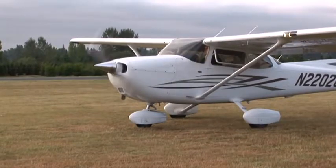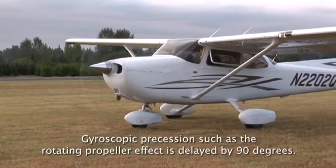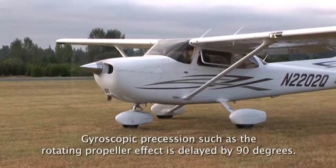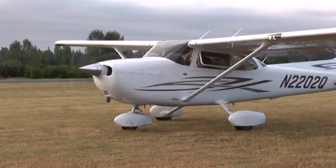Now, there is one other left-turning tendency that is often discussed, and it's gyroscopic precession. Gyroscopic precession is the result of a deflective force being applied to a rotating body like a propeller. Gyroscopic precession says that the resultant action occurs 90 degrees later in the direction of rotation. This is not to be confused with P-factor.